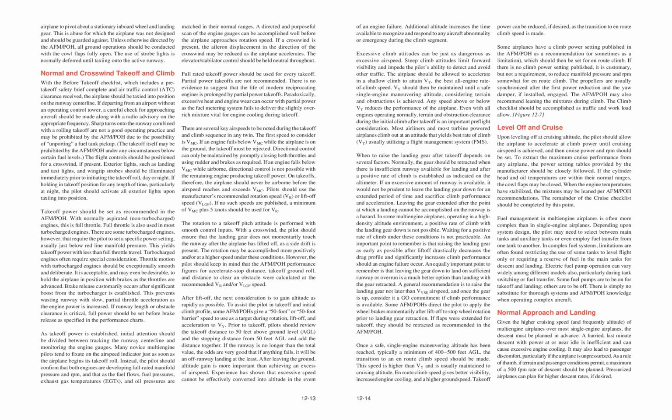An important point to remember is that raising the landing gear as early as possible after liftoff drastically decreases the drag profile and significantly increases climb performance should an engine failure occur. An equally important point to remember is that leaving the gear down to land on sufficient runway or overrun is a much better option than landing with the gear retracted. A general recommendation is to raise the landing gear not later than VY airspeed, and once the gear is up, consider it a go commitment if climb performance is available.